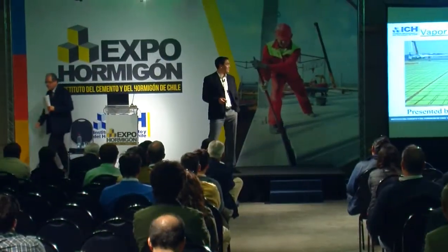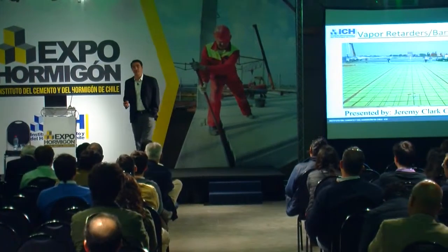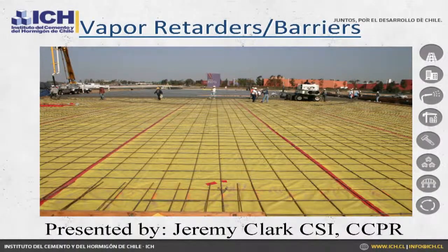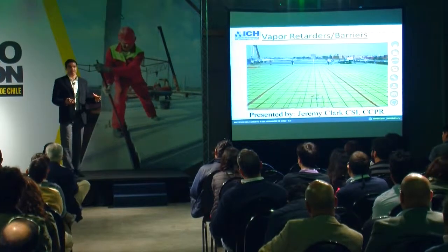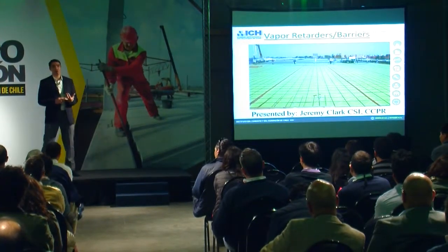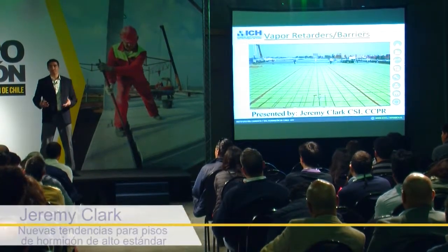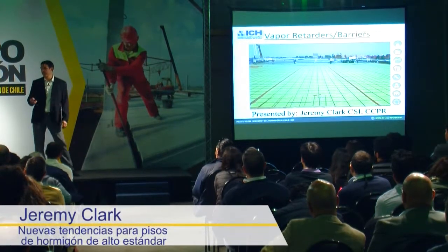Hola. So today we are going to be talking about below slab moisture protection. Installing a vapor barrier to prevent water vapor, liquid water, and gas from the soil moving into the building.